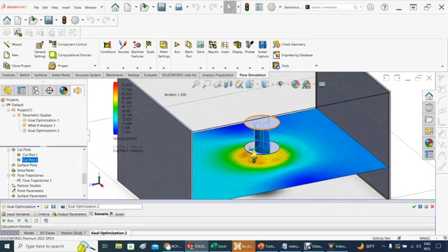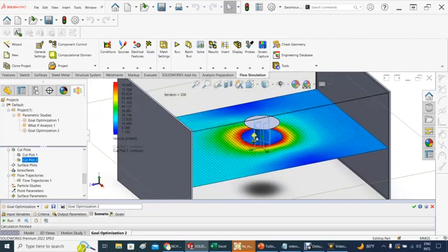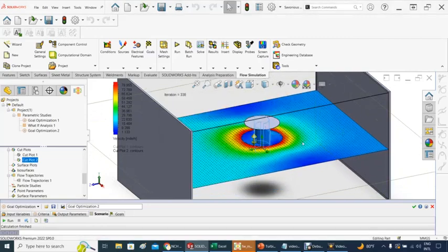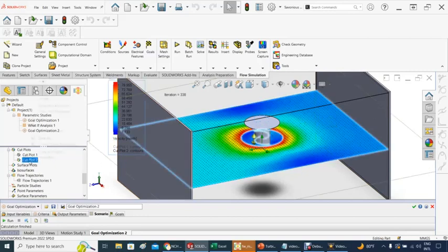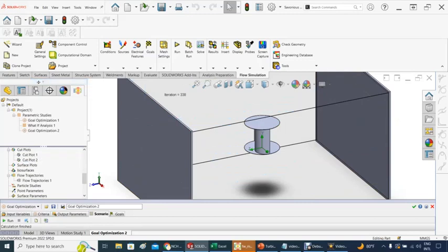It might have to do with the mesh that I was using. Remember that for the turbine itself, I used a very fine mesh, and I'm going to show you that in a second. But for everything else, for the wind tunnel, I stayed with a value of 3 for the regular mesh size. So let me show you that. Let me get out of here. And now let's show you the mesh, how that looks right here.